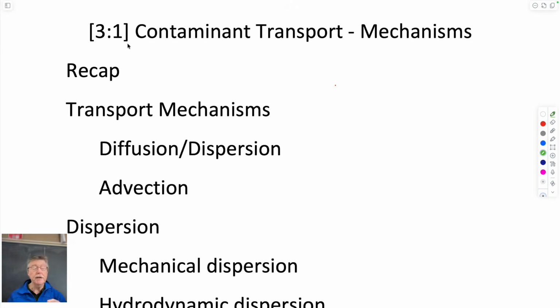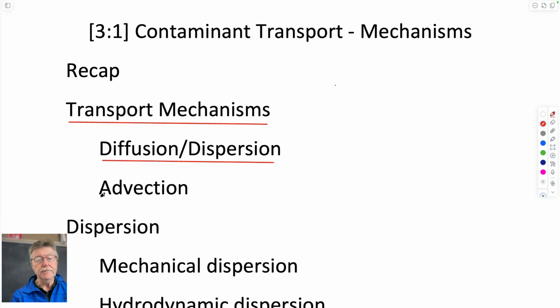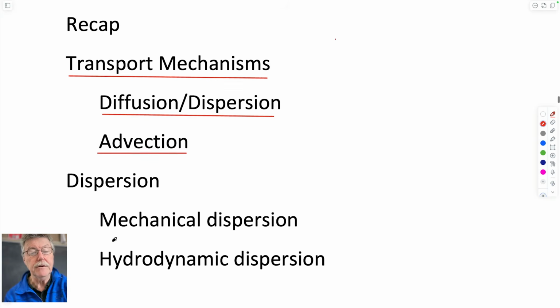It's important to make the mental change that now we're not looking at two fluids traveling at the same time. We're probably looking really only at water traveling in the saturated groundwater zone and carrying dissolved in with it something that really doesn't affect its motion. It's not heavy enough to stop it. It doesn't affect the permeability behavior very much. And so we can work with that. So we'll look at what the transport mechanisms are for advective flow and diffusive flow. We'll look at each of these transport mechanisms in turn. We'll look at the physical processes that affect these two behaviors.